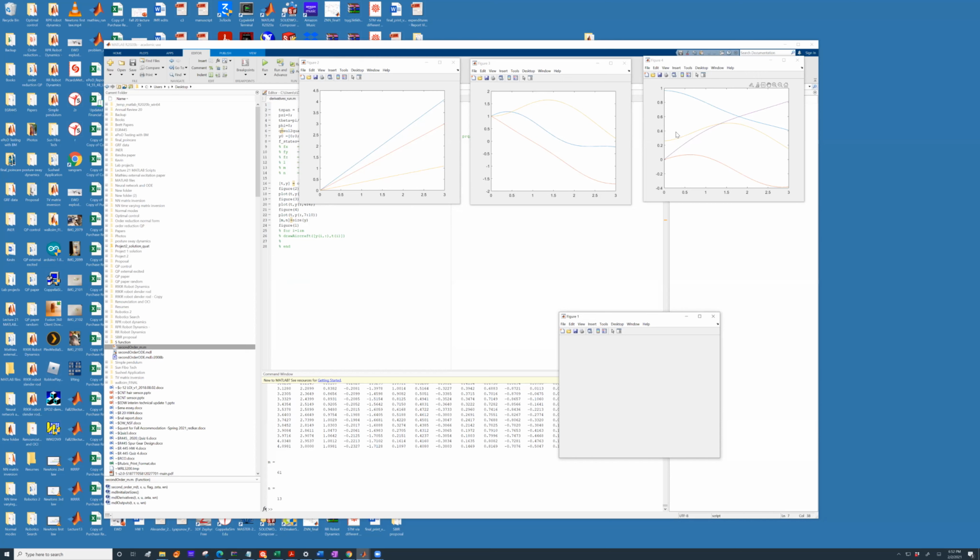And what would most likely happen is, if you had noisy sensor measurements, or if you have external forces, you can actually plot the norm of the quaternion at every time step. And you will notice that the norm of the quaternion may exceed 1, which means it won't be a pure rotation. Okay, I'll show you.